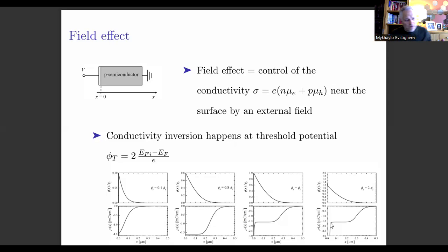So the value of the electric potential inside of the inversion layer drops dramatically, very quickly, and eventually it reaches the threshold value at which the inversion layer can no longer be supported. And then the depletion region begins. And it begins when the initial value of the potential where the depletion region begins is exactly the threshold potential.